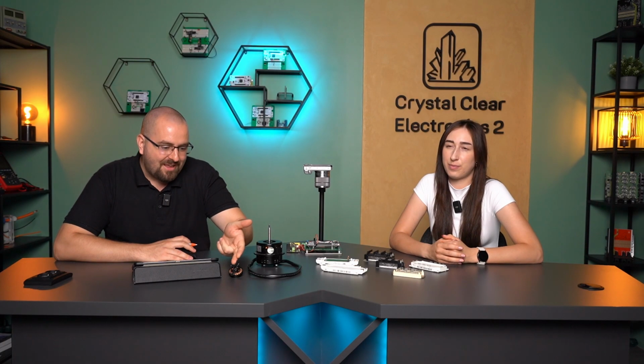To be honest, I don't like to classify BLDC motors as DC motors because they are not really DC motors, but 3-phase synchronous motors with proper motor control electronics. So you still need a motor controller to make them rotate. You can see that, as I mentioned, this one only has 3 wires.